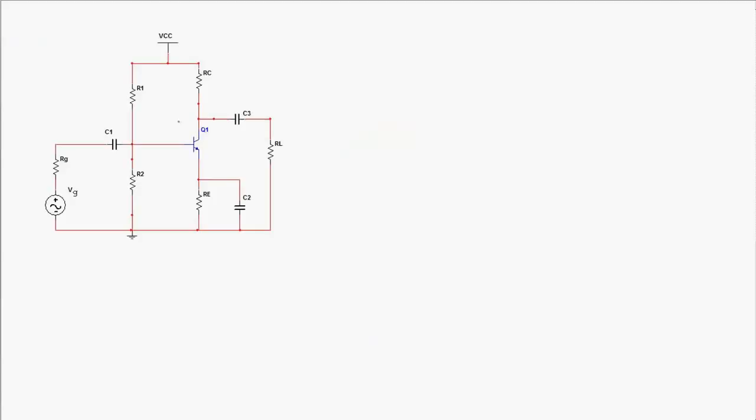I've brought it down here so I've got a little bit more white space to work with. Let's put some numbers into this circuit so we can work with some actual figures. Let's say we've got a voltage source here of 20 volts. We have one of our voltage divider resistors, this one's 50 kilo ohms, and let's make this one 10 kilo ohms.